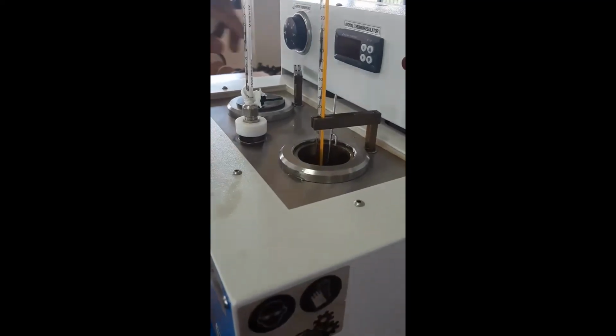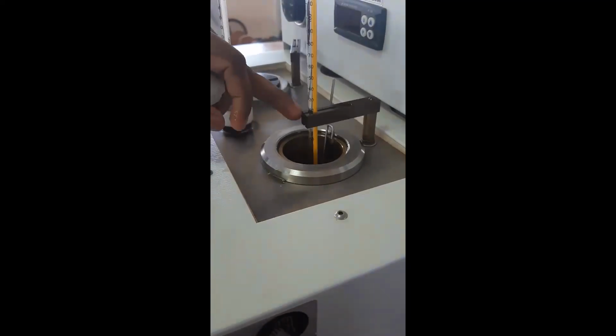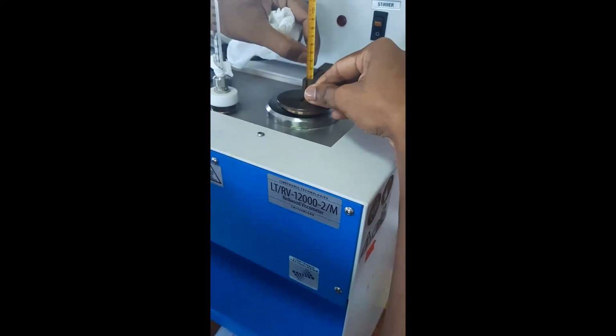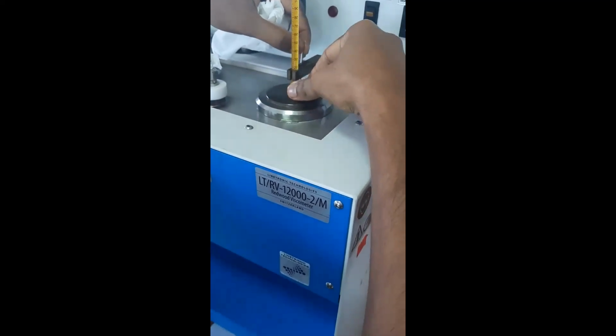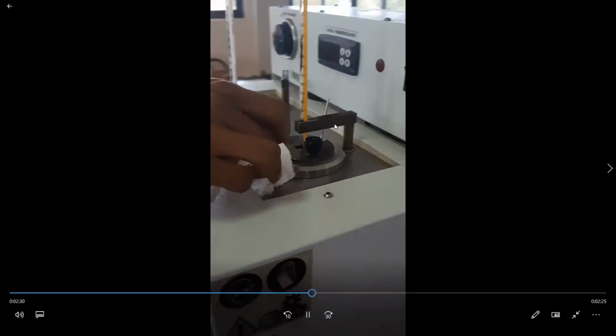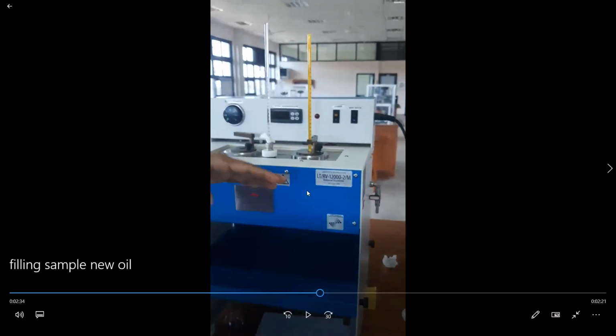You can see now this will block the oil flow. So after heating up the oil, we can lift this ball valve, then we can collect the oil from the downside, right? Because there is a stand. By using this thermometer, we can measure the oil temperature. We can hook the ball valve on that stand, right? Then the oil will flow continuously. Then we can collect from the downside, right?